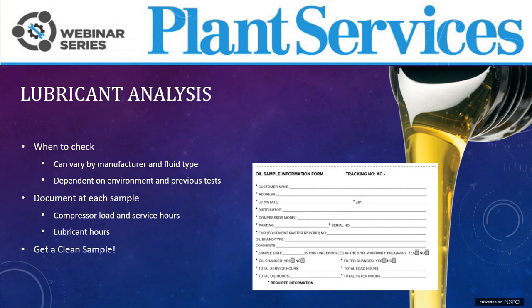Other things to consider are what's required at each sampling interval. The load and service hours of the compressor, along with the lubrication hours, are key. Another imperative is to get a clean sample. And as I just mentioned, compressor rooms and therefore the compressor itself aren't always the cleanest environments. If there's particulate on the oil drain, then those particulates are going to contaminate your sample. So getting a clean sample is going to help you with your trend analysis, no question.